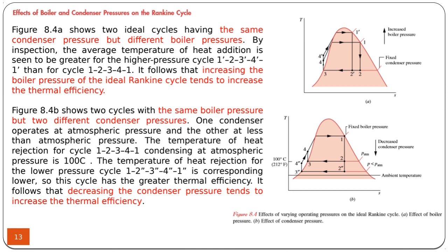As you see, the efficiency is related to the amount of work. As the amount of work is increased, then efficiency is increased also, because by definition, efficiency is net work divided by Q in. And suppose that Q in is constant, then if we are able to increase the net work, it's possible to increase the efficiency. And net work is the area under the TS curve.